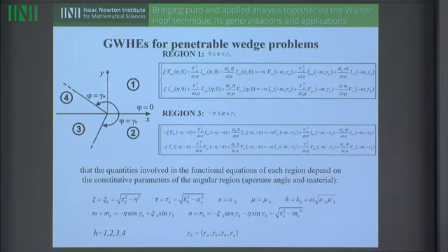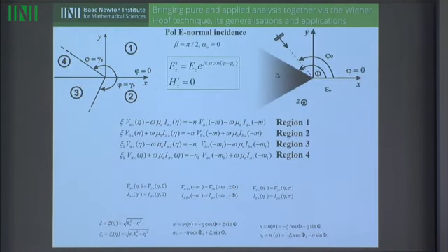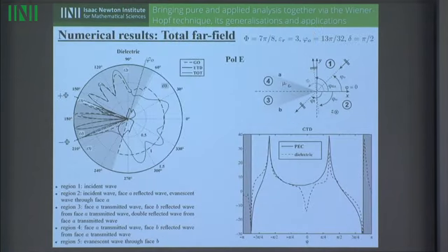Here are some parameters. I don't go into details. In this case, we impose continuity on the faces of the dielectric. Then there is a not easy procedure reported in the paper, and we get the solution of the field with all the geometrical optics components, all the GTD components regularized through UTD.